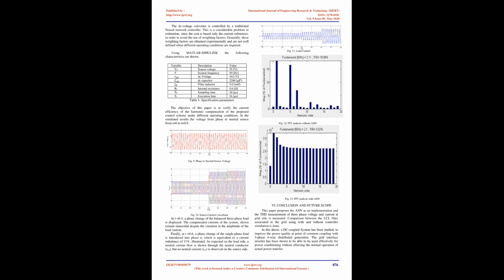However, the extensive use of equipment based on power electronics and nonlinear PCC loads generates harmonic currents that can deteriorate the quality of power. To obtain the current reference signals for the active power filter, a current reference generator diagram based on DQ is used. The synchronized reference signals are gained from a synchronous reference frame, SRF, PLL. This SRF PLL produces a pure sine waveform even though the system voltage is severely distorted.